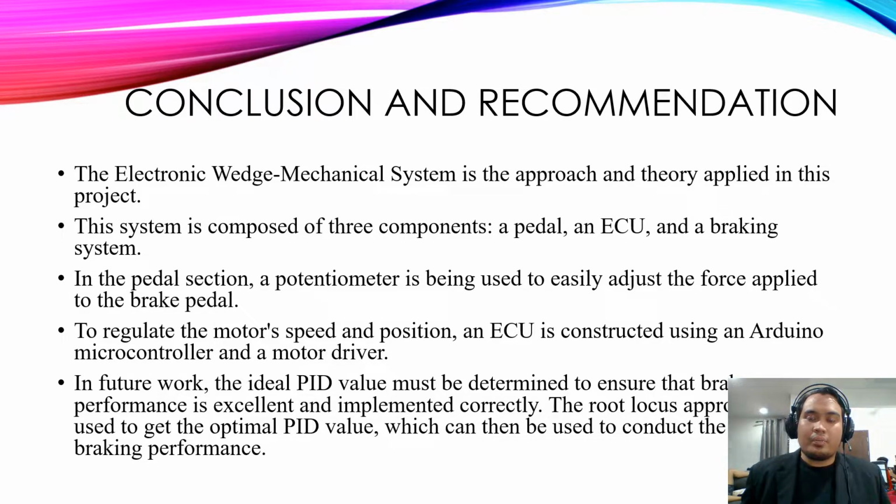So for the recommendation in future work, the ideal PID value must be determined to ensure that brake performance is excellent and implemented correctly. The root locus approach may be used to get the optimal PID value, which can then be used to achieve optimal braking performance. Thank you.